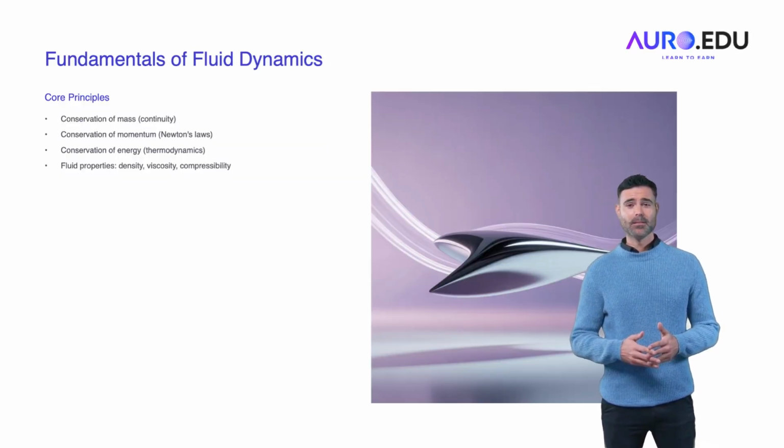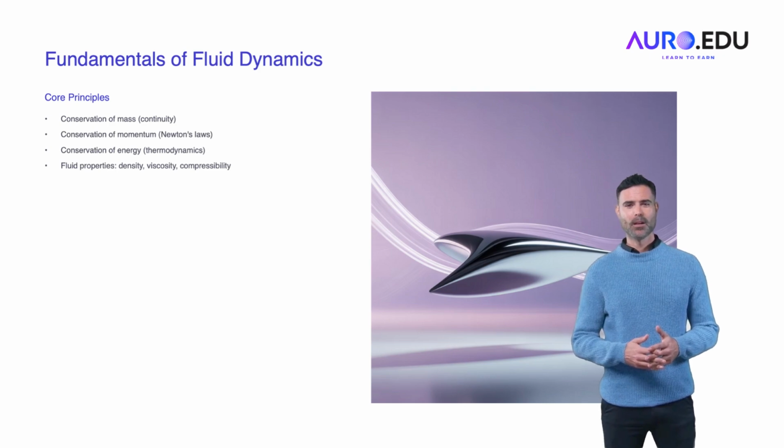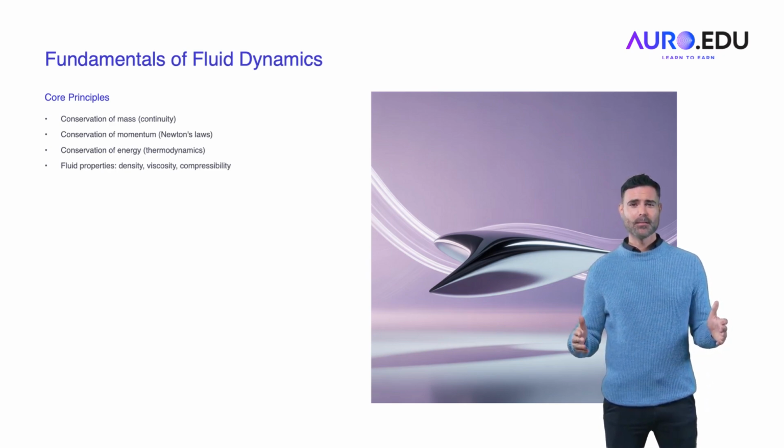Fundamentals of fluid dynamics. Fluid dynamics is the study of the motion of fluids, liquids, and gases, and the forces acting on them. The continuity equation ensures the conservation of mass in fluid flow, stating that the mass entering a system must equal the mass exiting it. The Navier-Stokes equation represents the conservation of momentum, describing how the velocity field of a fluid evolves under the influence of forces like pressure and viscosity. The energy equation is based on the first law of thermodynamics, governing the flow of energy within a system, including internal energy, work, and heat transfer.